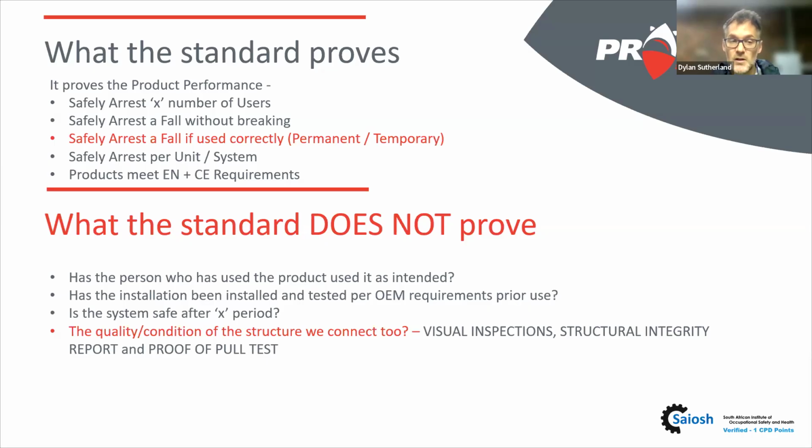And once again, we should be pulling it. So if it's into concrete, for instance, you can't always see visually if concrete's degraded. A pull test will tell you that. And the proof for you guys is, I want to see it being able to withstand that force for X amount of time. That will make me comfortable to let my people connect to it.